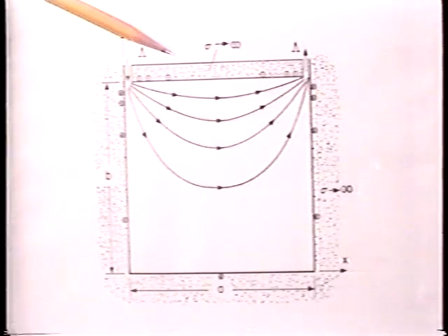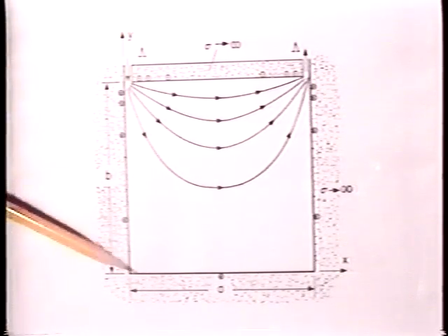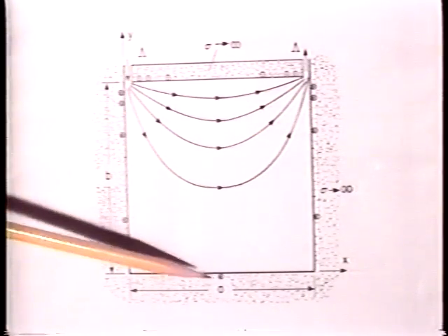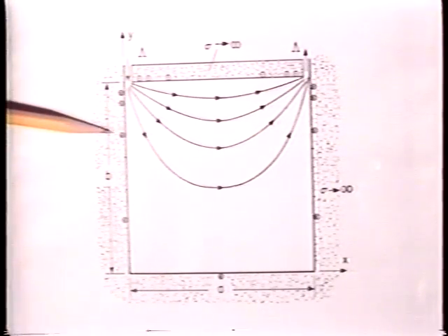A surface of constant vector potential is one that sustains no normal component of the magnetic flux density. It can be the surface of a perfect conductor. Here, these boundaries of 0 vector potential are perfect conductors, carrying that surface current necessary to terminate the tangential magnetic field.